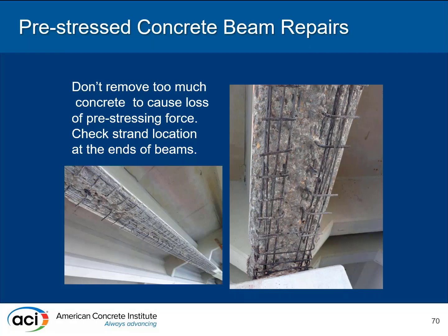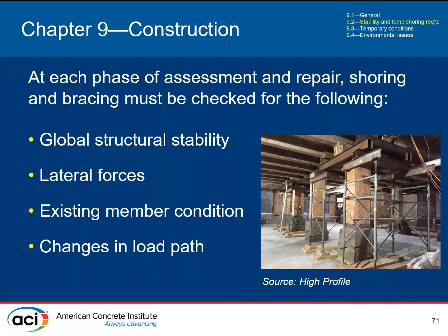So that's the construction chapter of 562, which provides direction that way. It also focuses on bracing and shoring, which is very important in new design as well. But the difference is, in new design, the designer is familiar with the final condition, but they're not aware of what's going on at different stages.